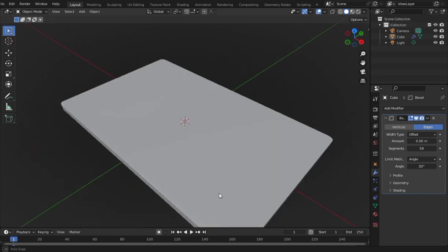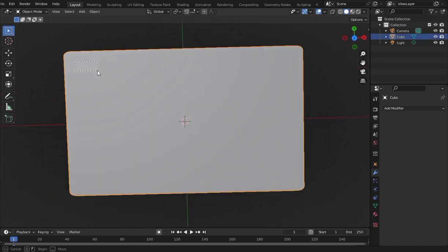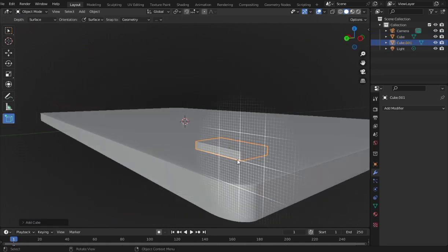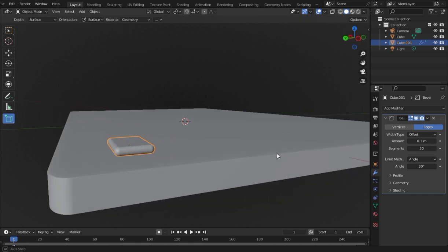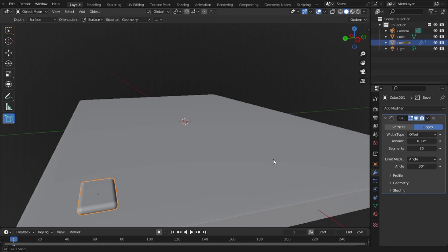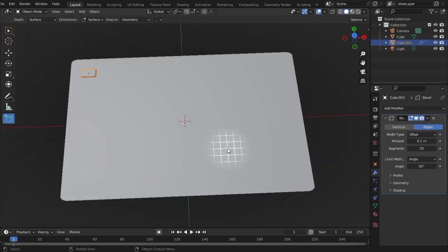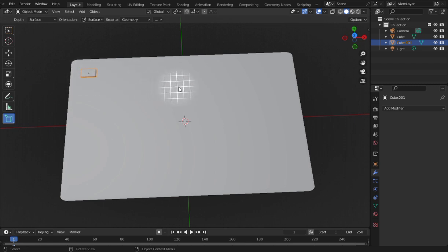Okay, so let's create the function key of keyboard. So take a little cube and go to modify menu, then apply the bevel effect. Increase some bevel volume, and now we can see the shape looks like a button. We will duplicate this. To duplicate it along the x-axis, we can use array function.